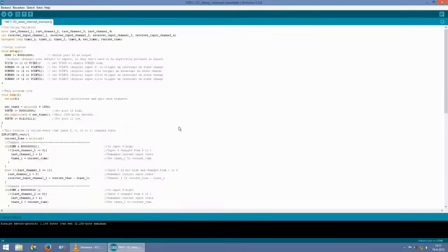Now to keep things as simple as possible, I found that the best way to create a pulse is by using the microsecond timer. In this example, the variable is loaded with the microsecond time increased with 1500 microseconds. The output is set high, and this while loop waits until the time is expired.